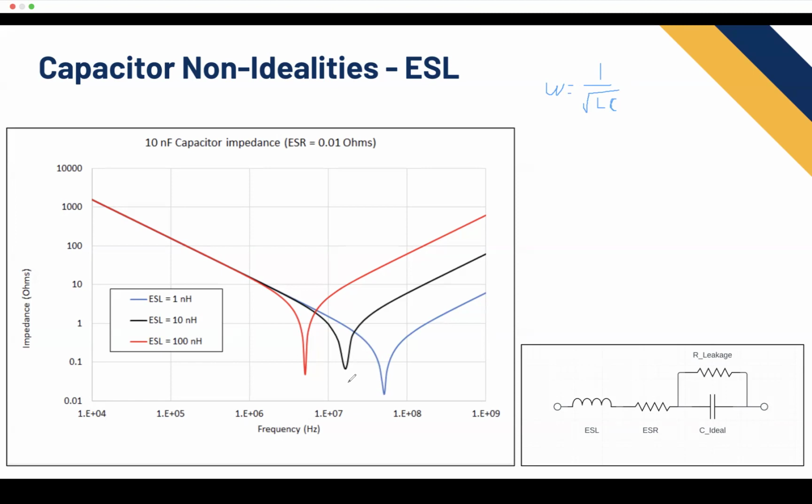If you imagine our noise is at some high frequency, you actually want to use capacitors of different orders of magnitude in order to get a graph like this, where you have all these capacitors in parallel, right? And capacitance in parallel sums.